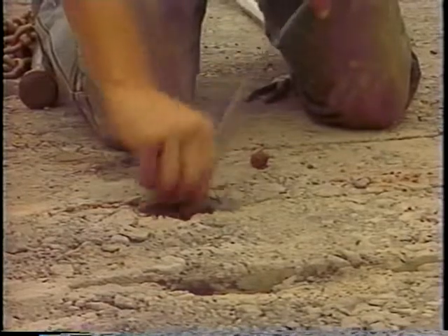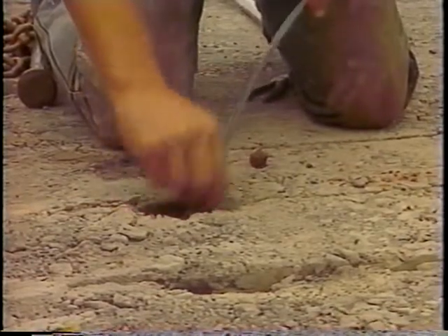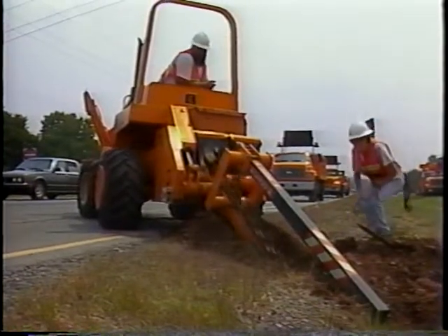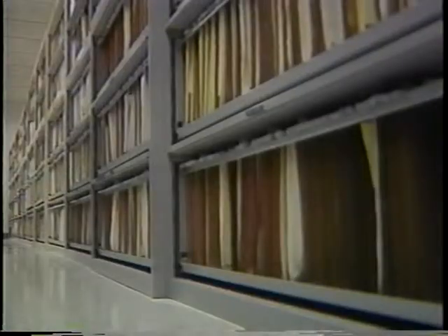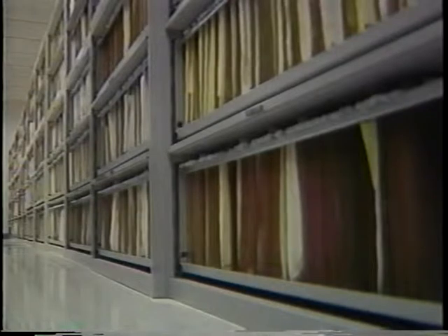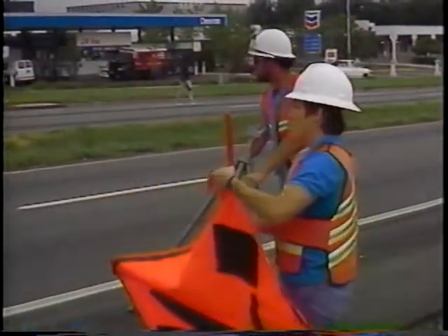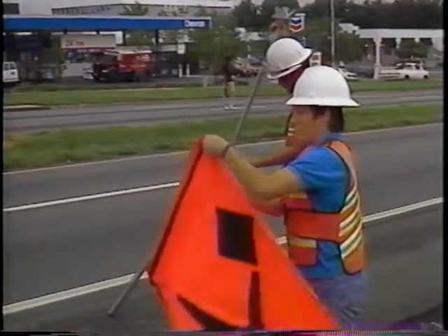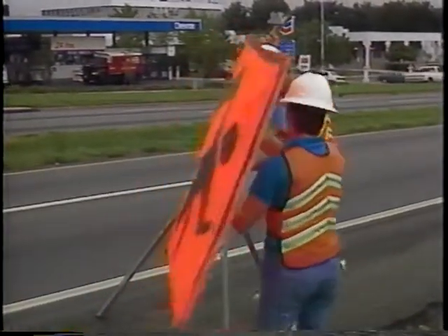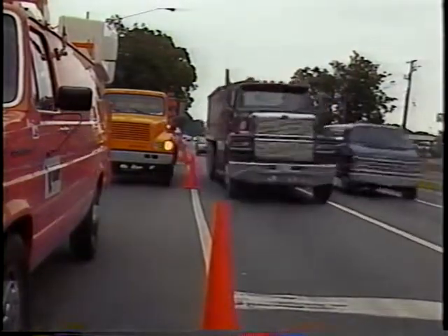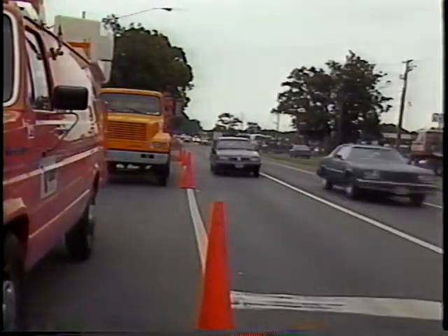As a result of this visit, you should be able to determine the method for burying cables. Choose the types of equipment required for the installation. Identify the necessary installation permits and licenses. And finally, determine the method of traffic control and rerouting that will take place during the installation. This traffic control and rerouting method includes the position and quantity of barricades and cones.